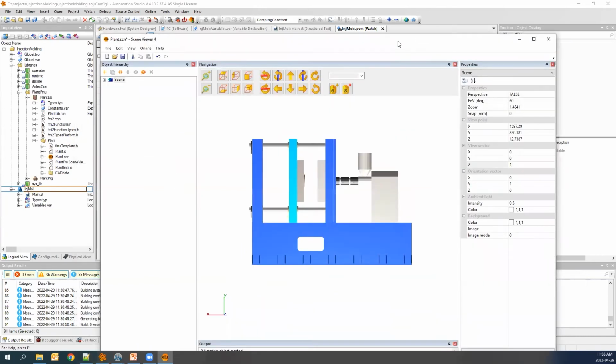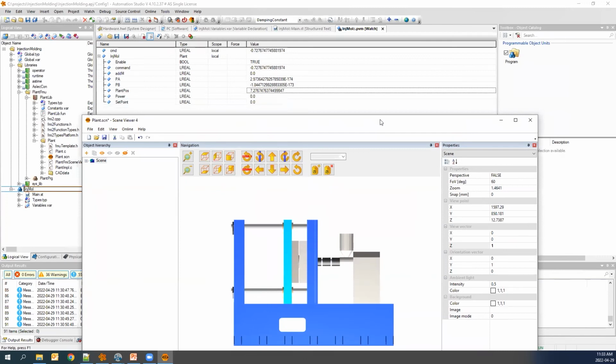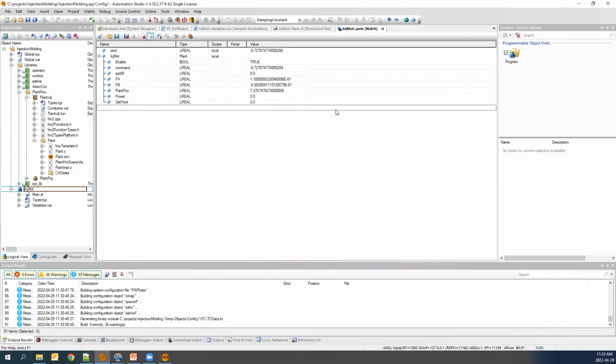And maybe just to highlight the point of, okay, well, it's nice, it's running, but I'm essentially running what I had in MapleSim, so it's not terribly exciting, so to speak. So now what I want to do is add some kind of additional flexibility in the code. I'm going to introduce a K parameter that's going to represent the proportional value in my controller. And then I want to be able to play with it. And that's really going to give you the sense of, okay, here's why that visualization might be more useful.